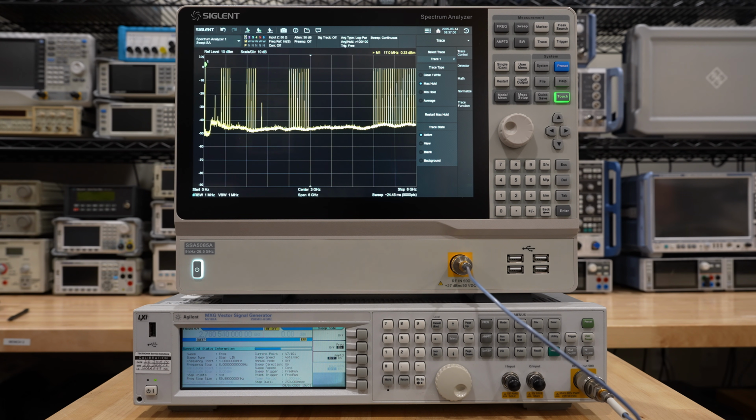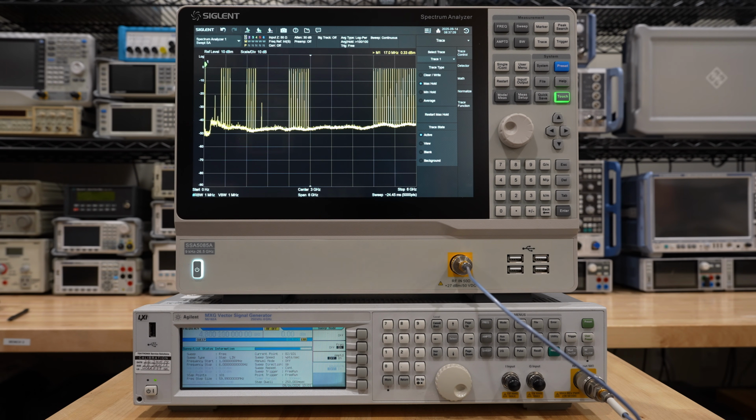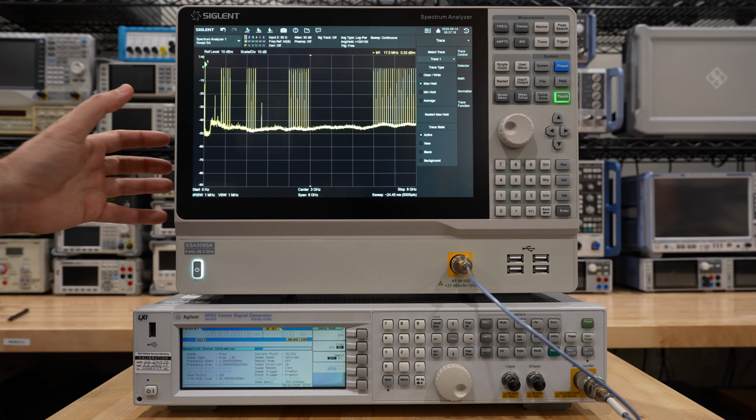Now, there are a lot of nuances when it comes to PLL analysis and PLL debugging, especially because depending on which direction you're sweeping, you're going to get a different reaction from the PLL. That's what happens when a PLL gets unlocked. There is a hysteresis in there, depending on the direction in which you approach it. So this is all going to have to be taken into account. But at least this is a little bit of a guide.